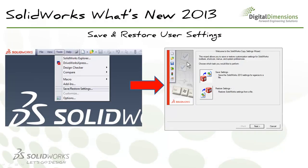The next topic I want to cover is called Save and Restore User Settings in SOLIDWORKS. Now, if you've ever wanted to transfer or copy over all of your keyboard shortcuts, file locations, and custom settings to another computer, you would typically use the Copy Settings Wizard. Now within SOLIDWORKS 2013, we can do this without having to close SOLIDWORKS like in previous versions, but simply by going to the Tools flyout in SOLIDWORKS, choosing Save and Restore Settings, and going through the workflow like we have in previous versions.